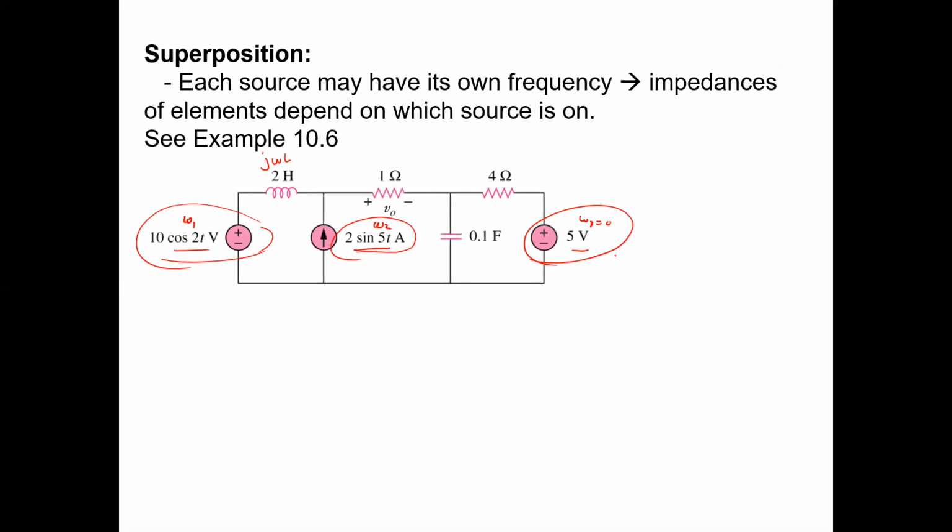So we can't just do a single Phasor transform, but we could turn off those sources and turn them on one at a time and solve for each one in the Phasor domain separately at different omegas, right? So that's where superposition is pretty good, because superposition just says you can solve it independently from each one, then you just add those results together for the total net.